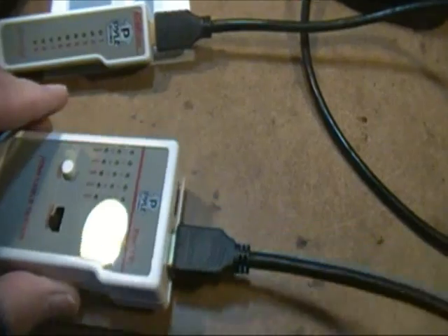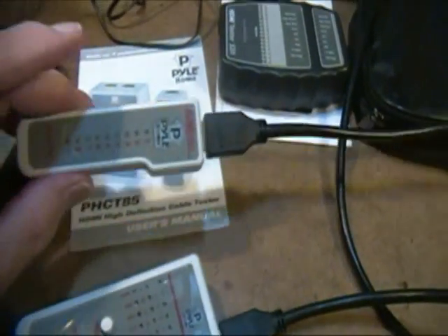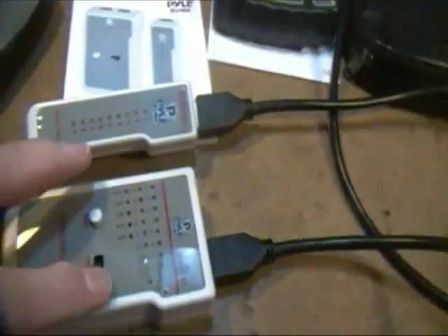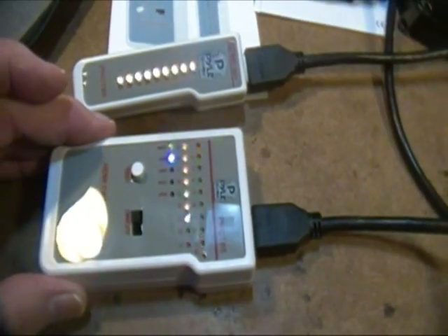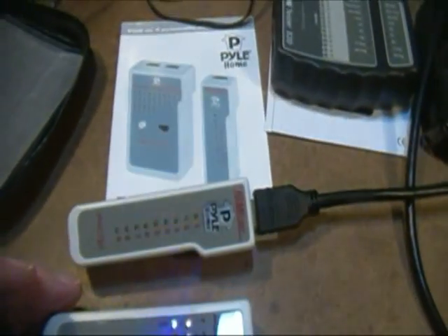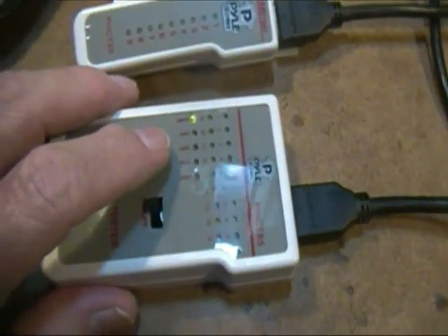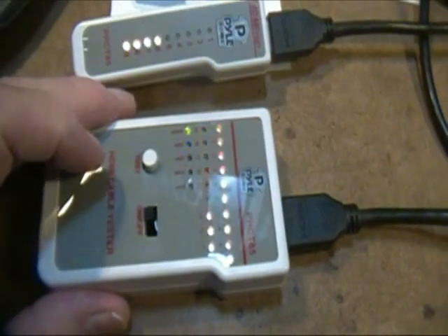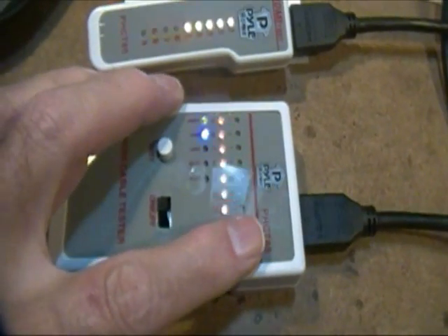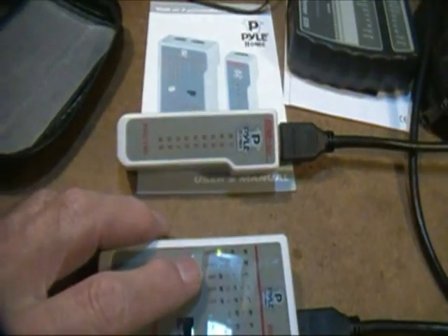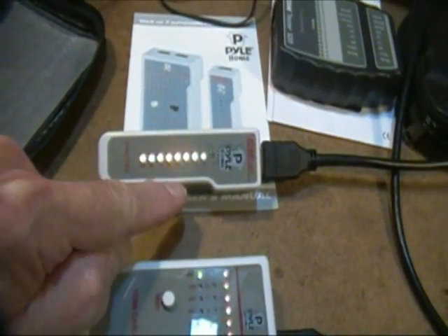Now I've plugged the remote end of this cable into the remote part of this tester, and now we'll power it up, and you notice it does the same thing, and it also indicates it on the remote end, which, by the way, that one does the same thing. The reason that you want that is you might have somebody working at this end who presses the test button, but you might not have communication to the remote end, and the remote end, by seeing this, when the person at this end pushes it, you see right away that it's working.